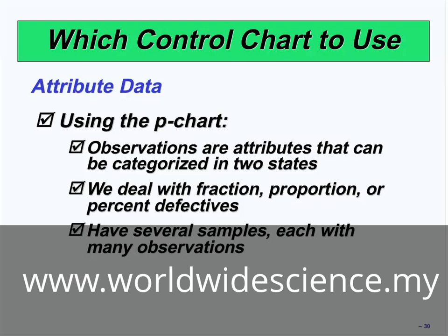In each time, they selected 100 unique products. So, 20 multiplied by 100 gives you 2000, the whole sample size for 20 hours. The number of defective divided by the whole gives you P bar.